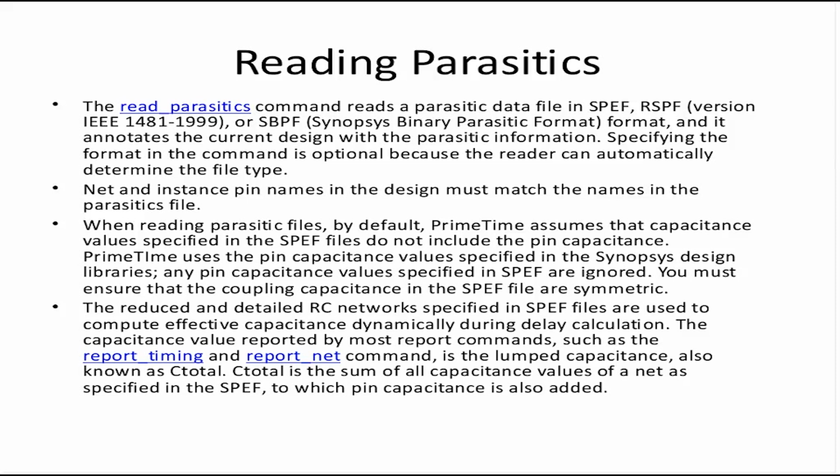Each input and each output of a cell has some inherent pin capacitance, and that capacitance value goes in the standard cell library, not in the SPEF. A SPEF will only contain interconnect data, not cell data, although it will tell us what the nodes are.